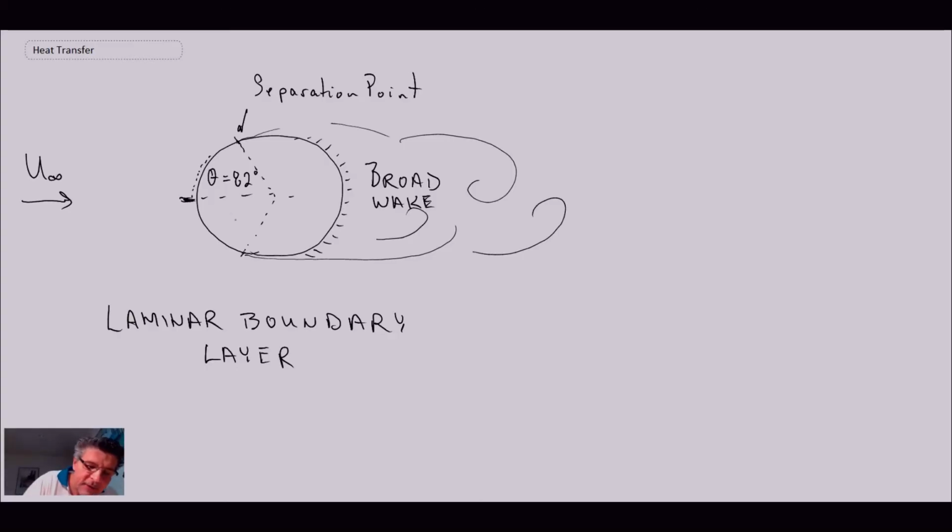And if we were to look at the drag coefficient for a cylinder with a laminar boundary layer, it's around 1.2. Now it's going to depend upon the Reynolds number. You got to be careful because a very, very low Reynolds number would be what we call creeping flow, and it would be a very different drag coefficient. But that would be, I'm guessing, a couple thousand up to the transition. Oh, here we have the critical Reynolds number, 3 times 10 to the 5, so I'll be getting to that in a moment.